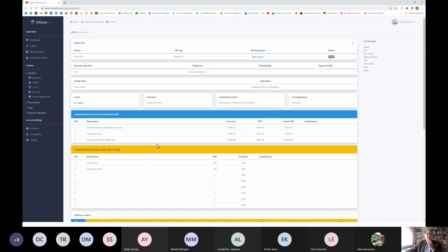Just one point in passing here, if you look at the American guidance for LOPA, they talk about only dealing with 1 cause-consequence pair at a time. I think their concern is that different protection layers can protect against different initiating events, and if you're not careful, that can be confused.